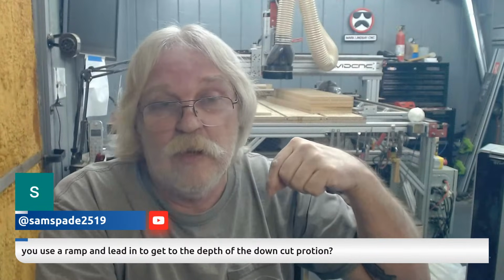Pete at Nature's Live Edge says, will you get chip out on the ramp in? If you're using a compression bit, probably. Until that upcut portion is buried below the surface, you're going to get chip out. And that's where the leads come in. Like Dave, a.k.a. Sam Spade, says, that's where a lead comes in. With a lead, you can start your ramping in, say, a half inch away from the actual vector, so that you know it's ramped in and buried before it gets up there and starts cutting around that vector. So ramps and leads working together, ba-boom.